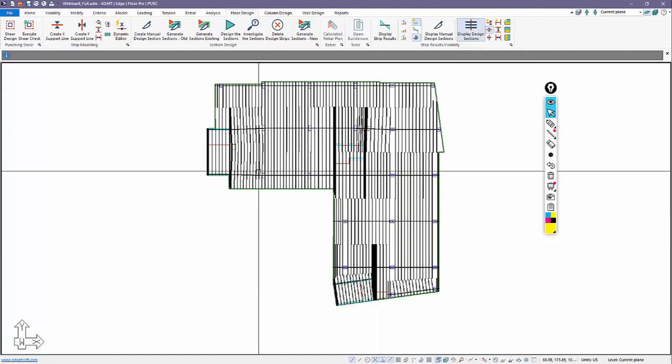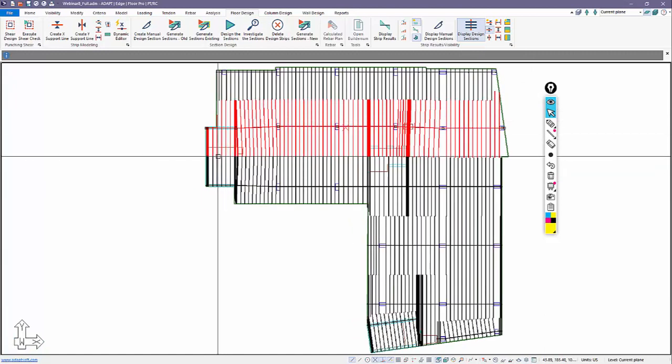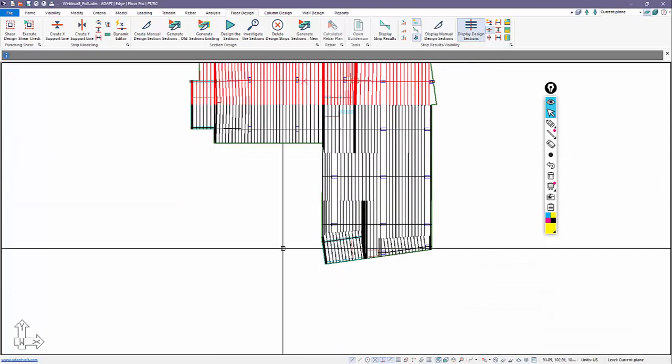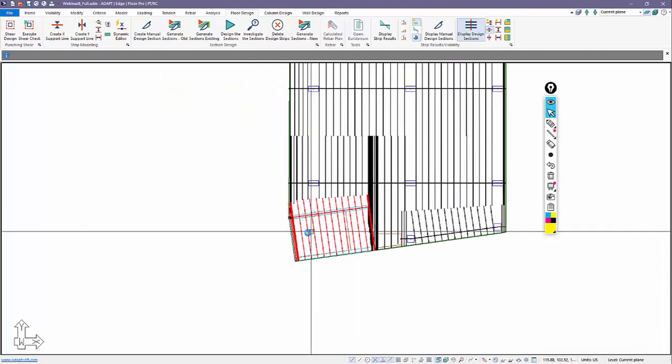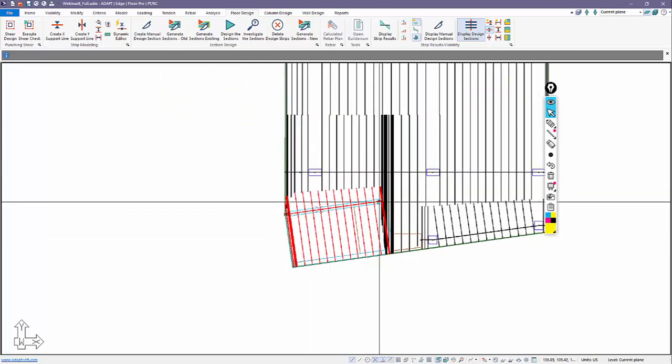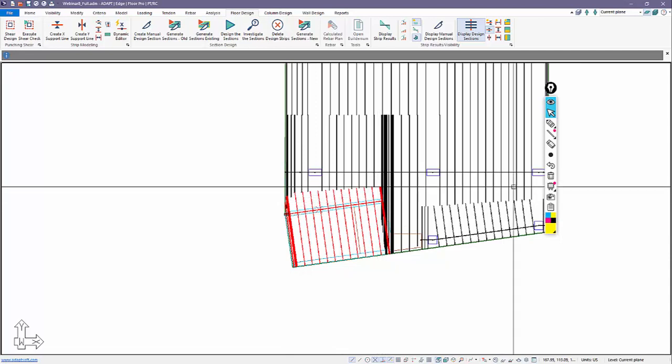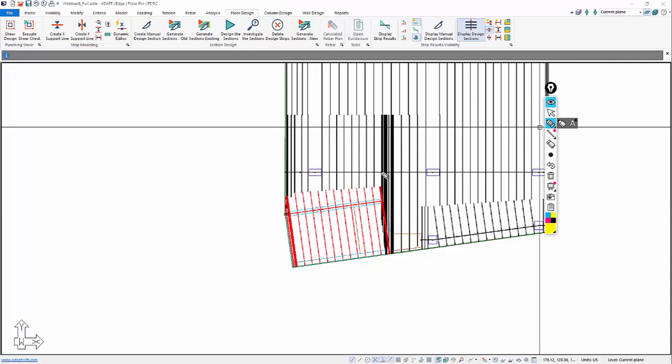If I now look at this direction, we still have this entering the opening. Again, technically that's not an issue, but what we'll focus on mainly for the time being is this. We can see that the program can now generate the strip based on your input of support line nodes without the need of any splitters. I did not put a splitter as I would have done in previous versions, something like this and maybe something like that. Those are no longer required. So splitters, by and large, will only be required as a boundary to terminate the width of a tributary region.